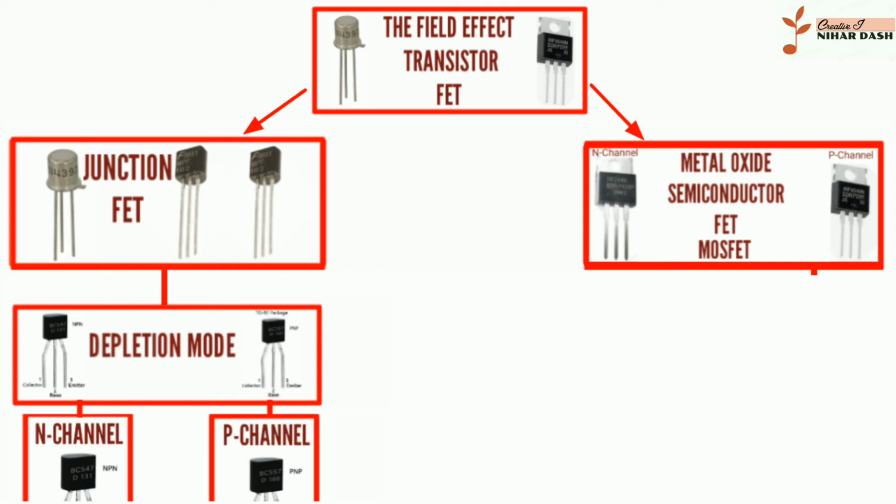The junction field effect transistor is a three-terminal unipolar semiconductor device that has very similar characteristics to those of their bipolar transistor counterparts. For example, high efficiency, instant operation, robust and cheap, and can be used in most electronic circuit applications to replace their equivalent bipolar junction transistor, BJT, cousins. Field effect transistors can be made much smaller than an equivalent BJT transistor, and along with their low power consumption and power dissipation, this makes them ideal for use in integrated circuits such as the CMOS range of digital logic chips.